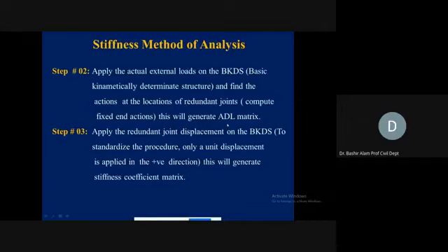Here, the basic kinematic determinate structure will be subjected to the actual loads. There, we found the displacements corresponding to the unknown redundant actions. Here, we find the fixed end actions corresponding to the unknown joint displacements. So here we are finding actions; there we were finding displacements.